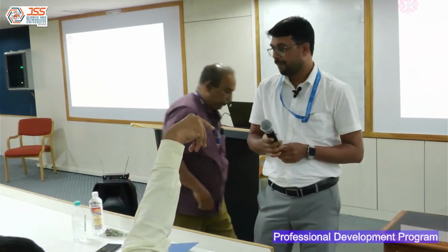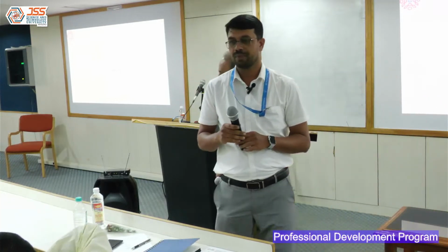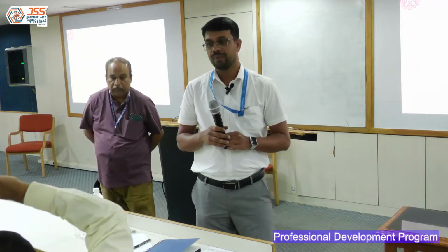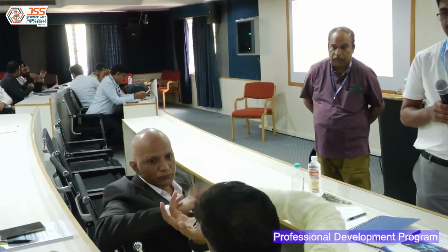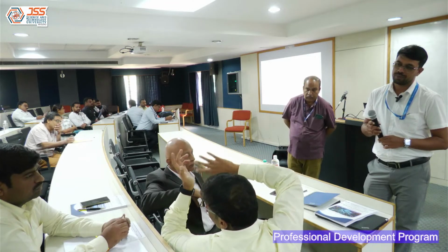That's why I told you about DFM, DFI, timing and all; these are the kinds of things we need to consider. We call it PVT, process voltage temperature. These characterize the model of your end product, whether it operates in a glacier or a high temperature place. Based on that, we have the library models available, and we do the sign off analysis on these library models: manufacturability, yield, timing, cost, maintenance, all this.